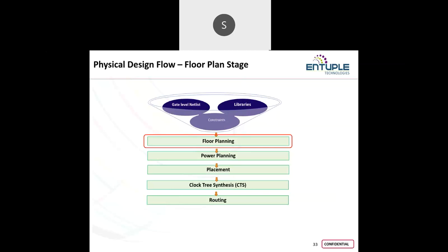To avoid that, users can make use of the command for setting the technology node. If I am generating any reports, in the backend the tool will call the default technology node. Default technology node means, for example, yesterday I ran a design with the 45 nanometer technology node. Today I am trying with the 90 nanometer technology node. If I am not setting any technology node, the tool will directly call for 45.